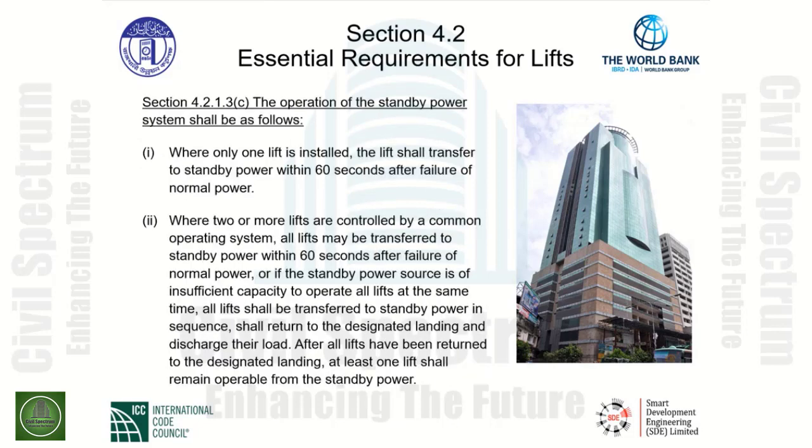The operation of the standby power system is specifically indicated here for the number of seconds that the generator must supply power. Item number 1 of section 4.2.1.3c tells us that where only one lift is installed, the lift shall transfer to standby power within 60 seconds after failure of normal power.